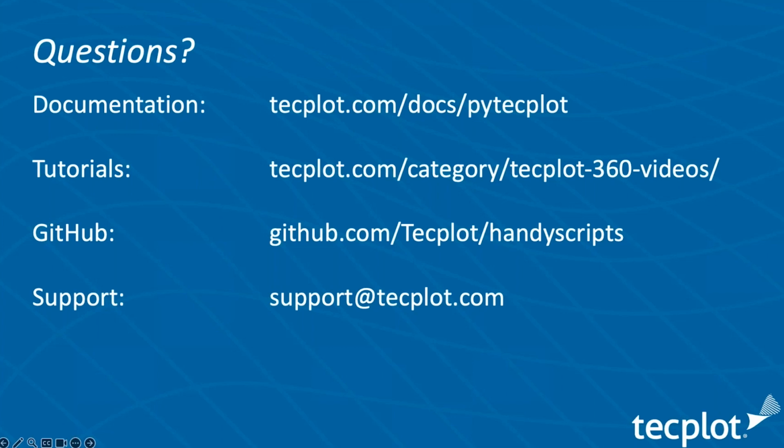There are some helpful tips for this online, but you can use pip to install locally, so you can install PyTecplot as a local package. That's totally doable with modern installs of Tecplot 360. And more information can be found in the installation guide in the PyTecplot documentation.